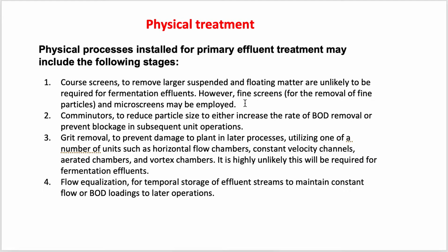Rather, the fermented effluents contain fine particles. So that's why fine screenings are used, not the coarse screenings. Coarse screenings are used to remove large particles. But as the fermented effluent may contain fine particles, fine screens are sometimes required. Even sometimes micro screens may be required.